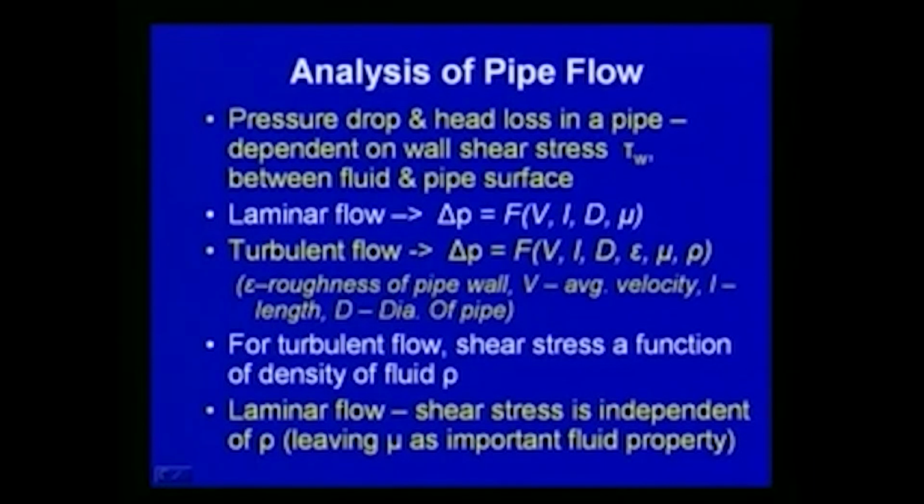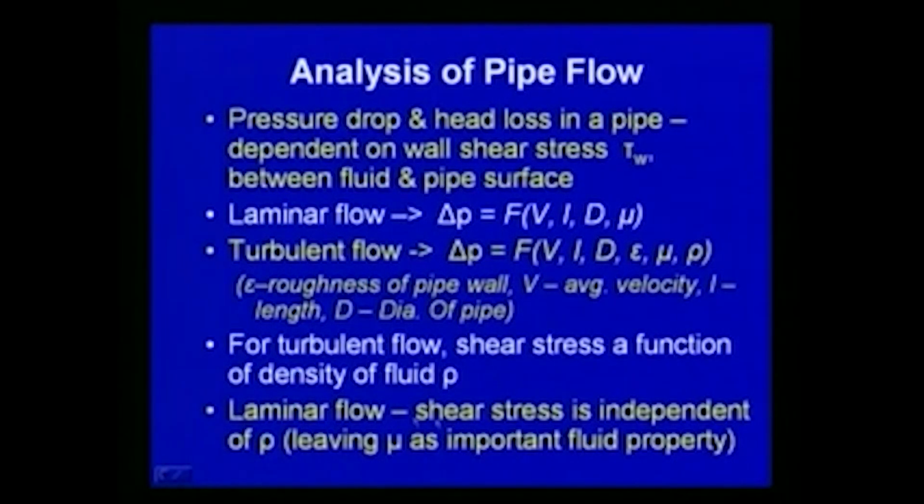We have to see whether we have to consider the roughness of the pipe wall, especially if it is turbulent flow. And also with respect to laminar flow, the shear stress is independent of the density rho, but as far as turbulent flow is concerned, shear stress is a function of density of fluid rho.